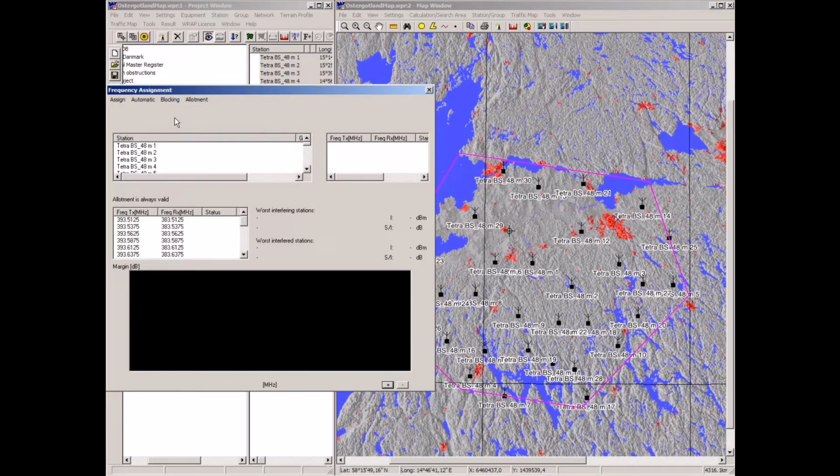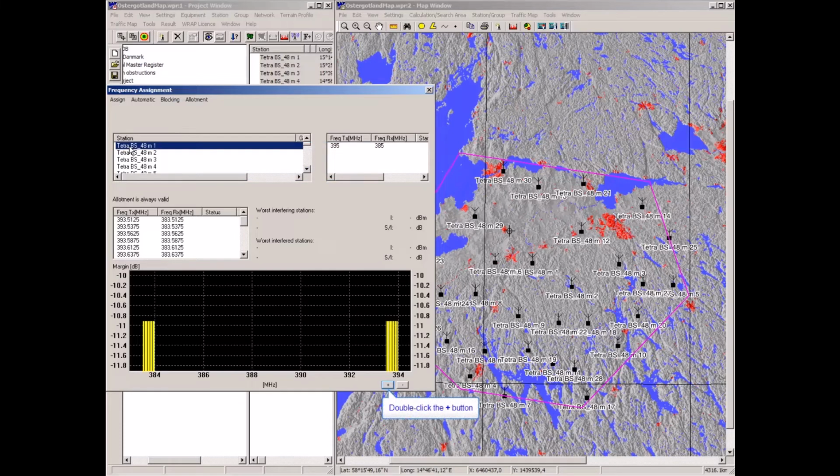And pressing calculate will then perform calculation now of all interference paths and wanted signal paths in this network of 30 base stations. So there are a lot of calculations going on now to position the mobiles at worst locations from an interference point of view, within the limitations that we gave for the blocking calculations, such as maximum 15 kilometer server range. Now it is ready.